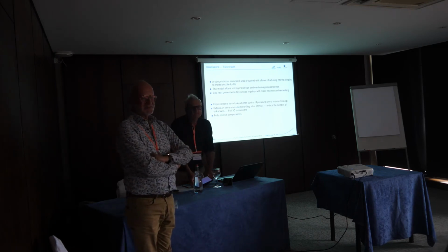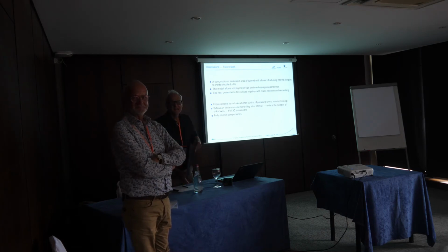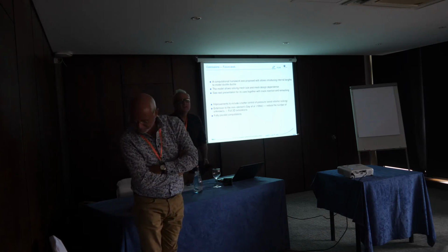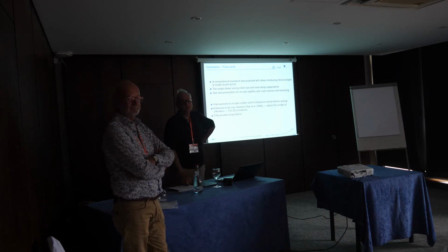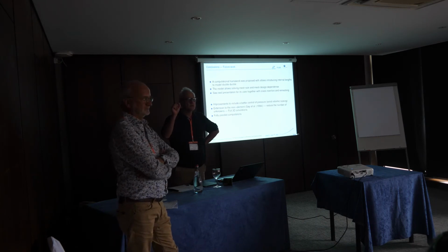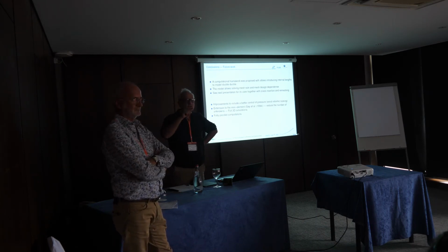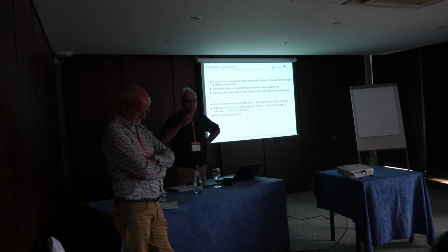Okay, other questions? Yes, please. I just need a small reminder, for the second length scale you are using, it's nucleation? Yeah, that's nucleation. And once again, that's nucleation of secondary particles, not nucleation on the primary inclusions. We always assume that the primary inclusions are there from the very beginning and that they nucleate very early. So we consider the volume fraction of the primary inclusions as voids.